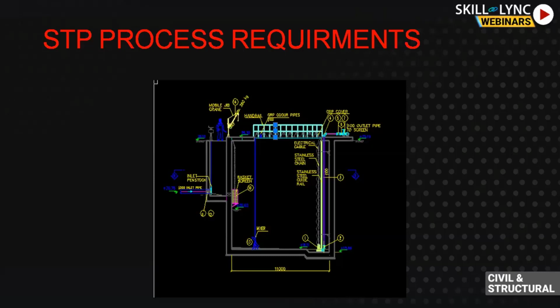What should be the size of the jib crane? If there is a person standing there, you should take the live load. He will tell you if he needs grating here or not. If he doesn't need grating here, you will provide an RCC slab. If he needs grating here, you have to provide it. This is where interdisciplinary coordination is very important.